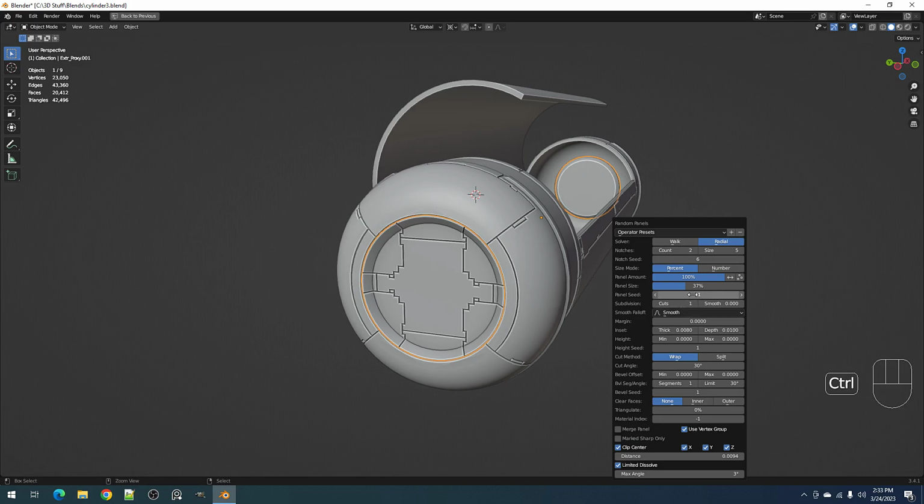If you see a random seed that you like, you can just Control C while hovering over the property and go look at some more. And if you want to return, just Control V to paste, or remember the number and type it manually afterwards.